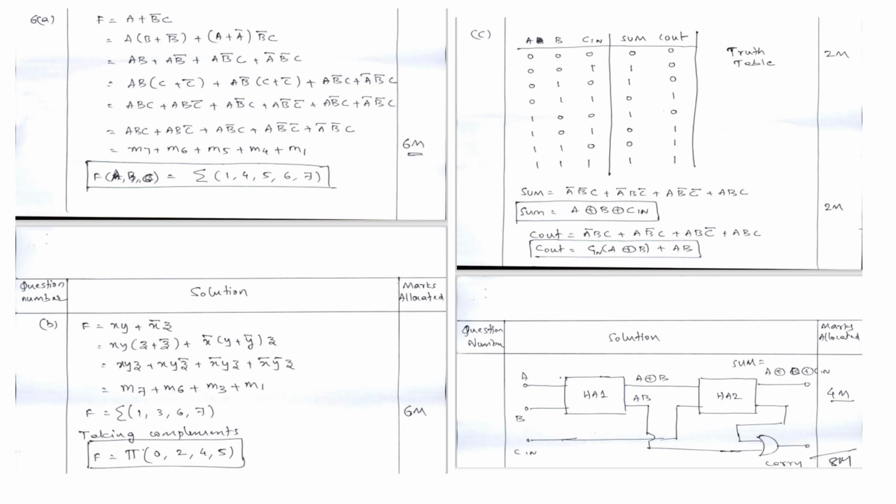Similarly, you will be determining the max terms. And here C is nothing but you will be determining the full adder with implementation of two half adders. So you have two half adders where you have two inputs to one adder and two inputs for the other half adder, and then you have a common carry. So A plus B plus C. Now when you are putting A plus B plus C, then you will determine the sum and carry using the truth table and the formula.